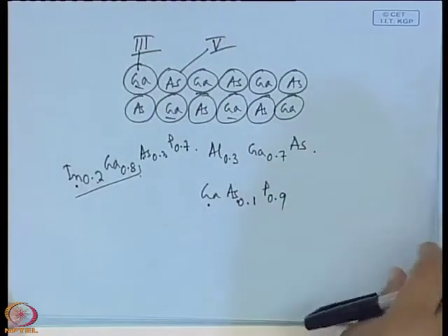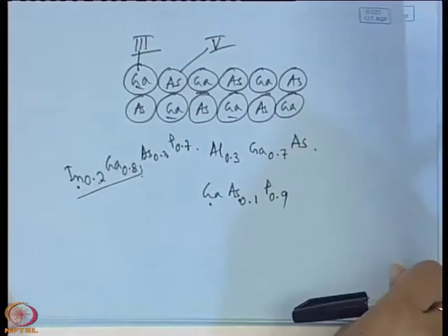Okay. Now, the implication of... So, can we mix the 135 and 126? For p-type doping, one element from the second group. It is not related to doping. Doping is not related, because if you dope the material, the band gap does not change. I am talking about band gap engineering, where I want to make new materials to tune the band gap for a particular application. The band gap does not change during doping.